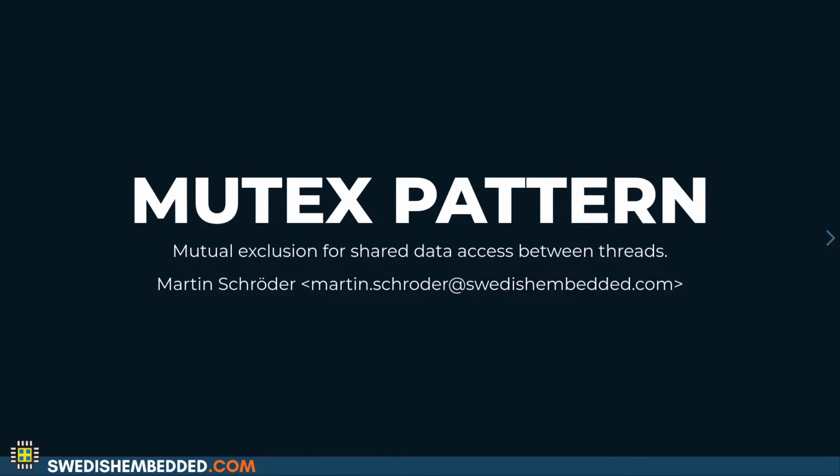In this module, we're going to look at the Mutex pattern, and this is the primary pattern that we use for mutual exclusion between threads. So we talked about the spin lock pattern, where we can get mutual exclusion between CPU cores and between interrupts and other code. We looked at the semaphore pattern, which we use for signaling. But when we want to do mutual exclusion between threads, there are a few more things that we need to take care of. And so we need to have a separate pattern for doing that, and we call this the Mutex pattern.